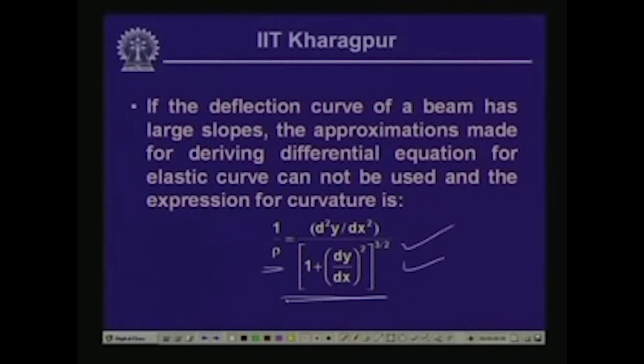Hence, the expressions which we have derived here are suitable for small deformation only, and for large deformation they are not applicable. We will have to use the curvature in terms of this expression. We are not going into the detailed derivation of this, but for your information, for a large deformation of the beam, the curvature term is to be used with this particular expression.